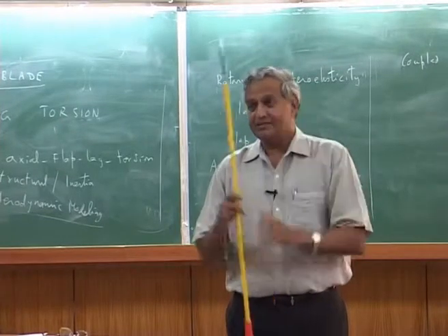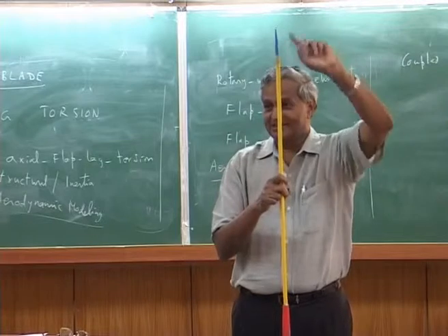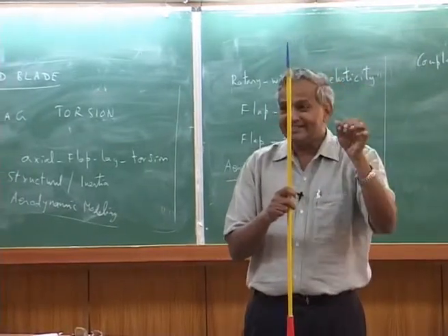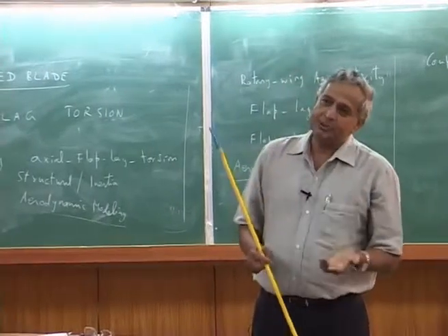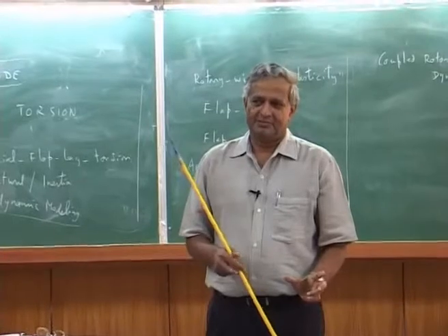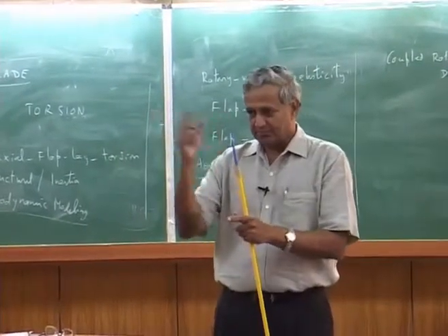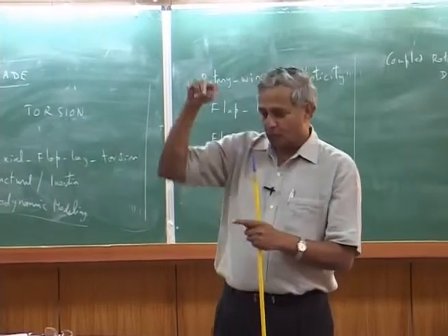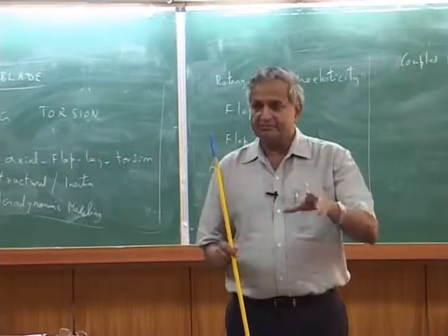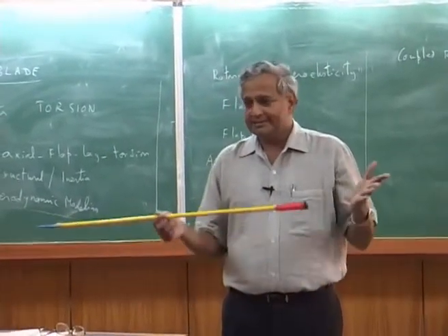Earlier they put some chalk and then brought a cloth. They will know where each color chalk hits. Then they will know, oh, this blade is high, that blade is low, then they change it. Another way is vibration measurement. If blades are not tracking the same position, you will have a 1 per rev vibration. They will try to minimize that. Okay, and that is the way.